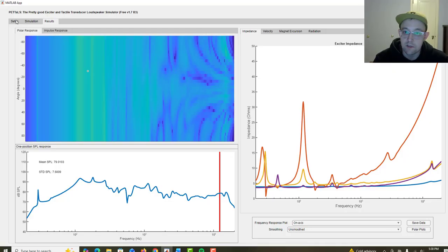So what's the blue one? Was that the... That was the 19CT4. Yeah, so that one doesn't have much impedance relative to these other ones. Cool. Yep, so that's the impedance of each exciter separately on the same panel. Pretty wacky response that you get here. It's actually not a terrible response, but I guess if you just cover a panel in exciters and drive them all, then you probably get something that's not that far away from piston behavior. So that's not super surprising, I suppose.